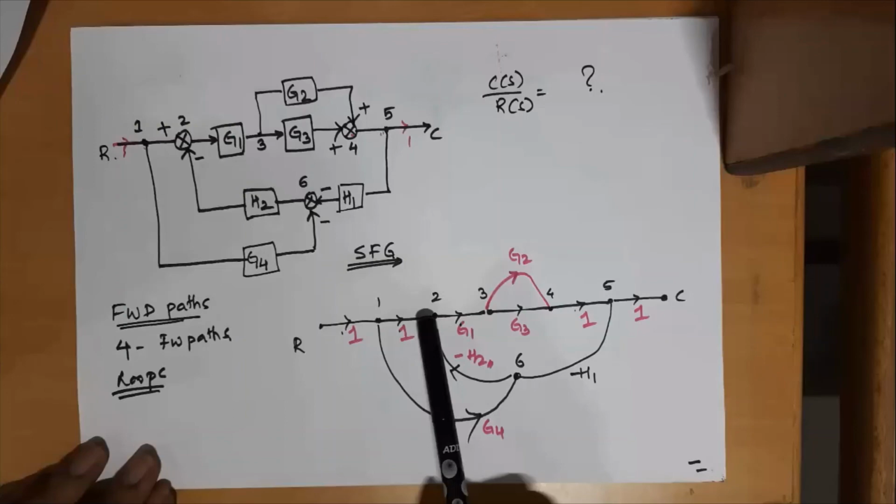And then comes the weight of the drone. You cannot ignore the weight of the drone. To design a controller, you need to consider it. So mass will come into picture. Fine. Then where is the spring effect? If you want to include a spring effect in the drone modeling, how does it affect? Then comes air drag, gravitational force, all those things will come into picture in mathematical modeling. So after understanding only, you can proceed. Okay, I have understood the system now, let me design the controller.